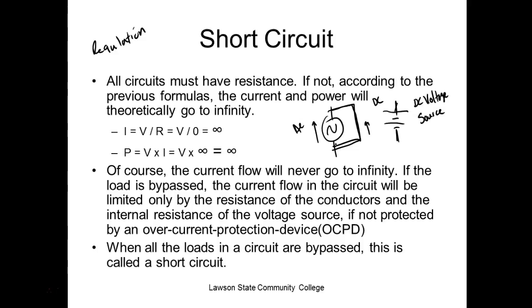So what happens on these regulated voltage sources is as the resistance of the wire goes up, you're thinking the current's going down, but it's not. Because the regulator keeps doing what? Going up. And the wires get hotter because now you've got a bigger R, right? You understand. You still got the same maximum current. You've got a bigger R, the wire gets hotter.